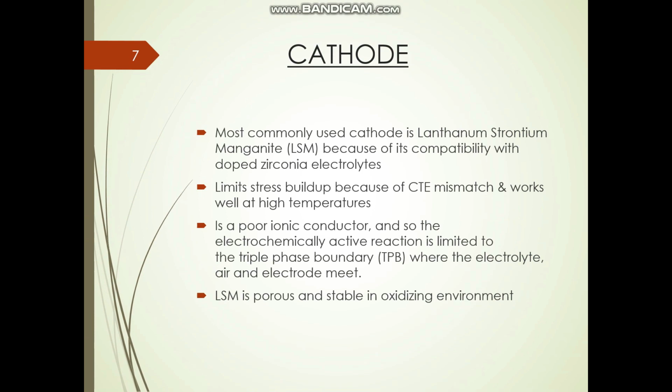Another porous constituent commonly used is lanthanum strontium manganite, which acts as the cathode in our fuel cell setup. It's majorly used due to its compatibility with yttria stabilized zirconia, as the coefficients of thermal expansion of these two are nearly equal, thus limiting stress buildup. However, it is an ionically bad conductor and so the electrochemically active reaction is limited to triple phase boundaries.